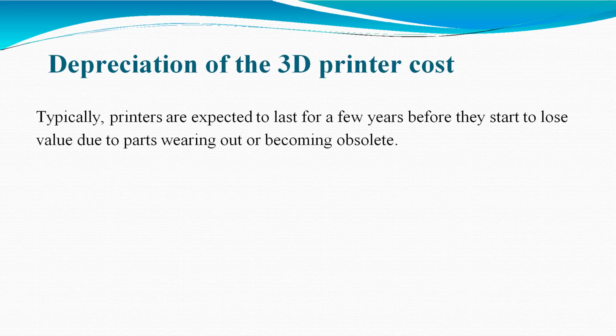And then the fourth is depreciation of the 3D printer. A 3D printer also has a life; it does not have infinite life. Some 3D printers have 5000 hours, some 2000, 3000, whatever it be, but we have to consider the depreciation cost of the 3D printer also. If the 3D printer is working for 2 hours for that particular product, we have to calculate the depreciation cost for 2 hours and add it.